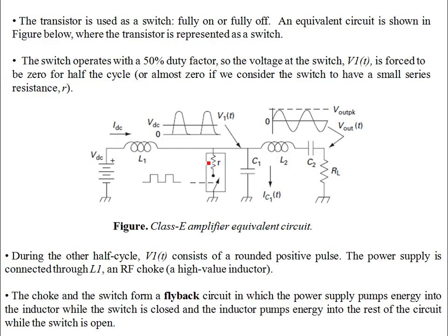So over here, we have a short circuit. This R is zero, so we have a short circuit. Now, as you can see, when the switch closes, this node, which is V1(t), it's the same node over here, is equal to 0. You can see there are pulsating zeros. Zeros are repeating when the switch is closed. So this happens when the switch is closed or the JFET is on.